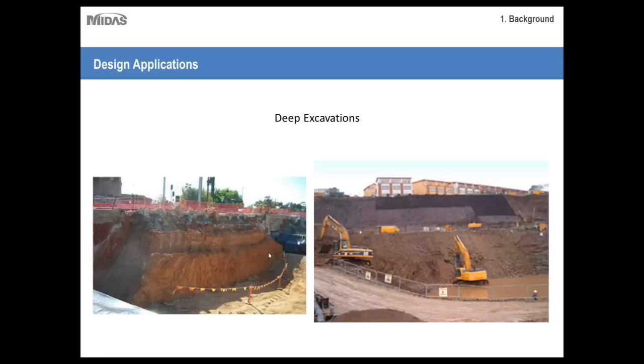But depending on the type of soil, so the soil to the left here is actually very clay soil, as you can see, it can stand very firm on its own as long as it's not too high. So that's another important design consideration: the type of soil that you're excavating into.